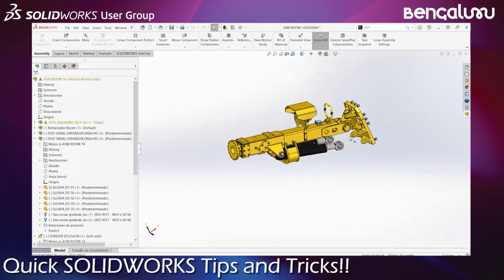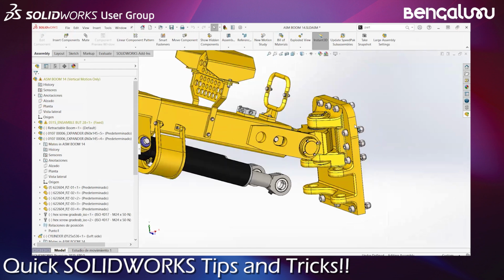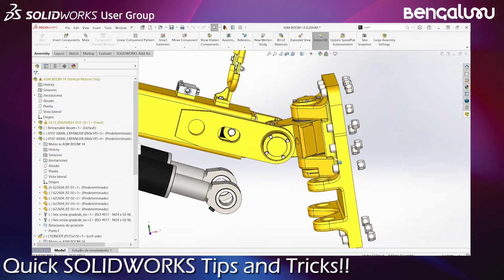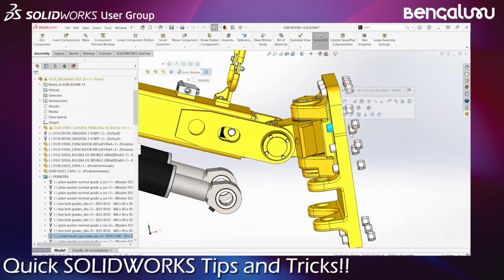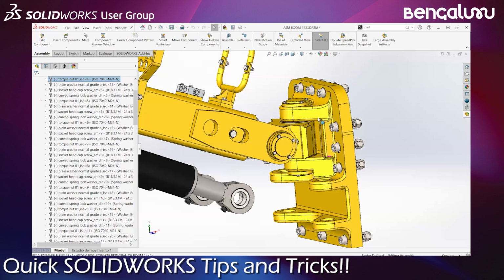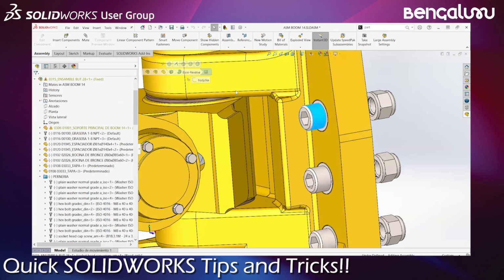Whenever you open an assembly, the first thing is selections. For example, I want to select all these toolbox components and hide them. The typical way is either to select them from the feature manager tree or from the graphics area itself, one by one. But the simpler way is I can select one component, and in the selection tools, there is something called select identical components.